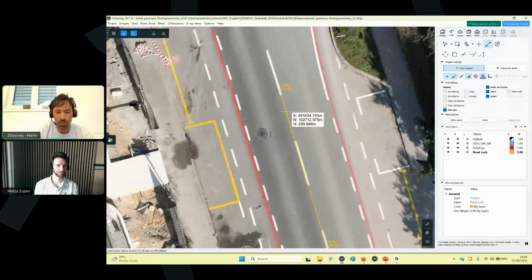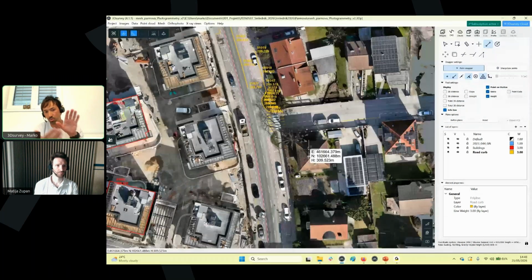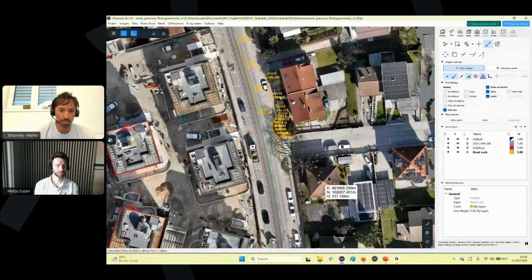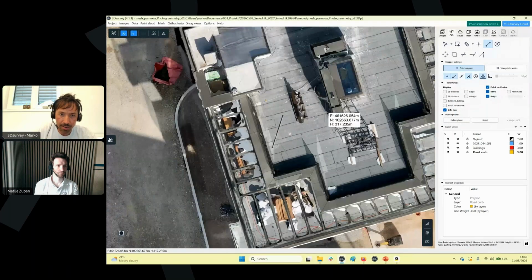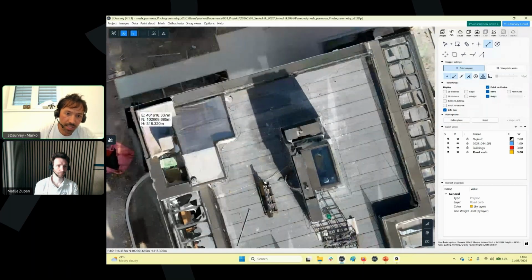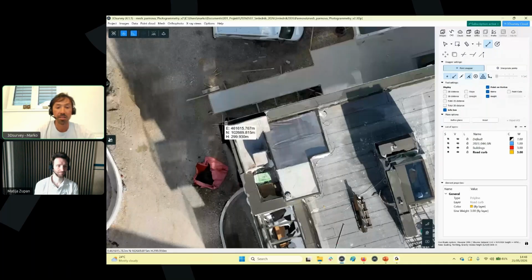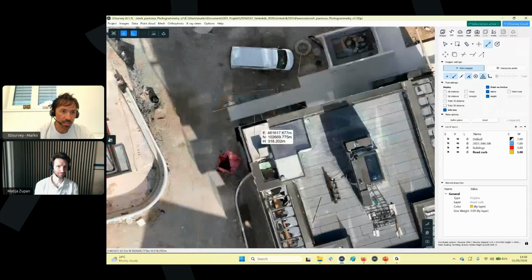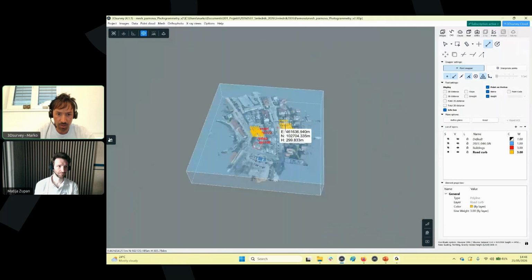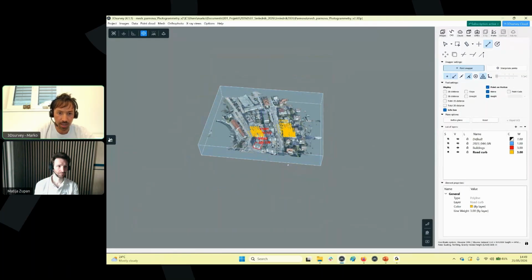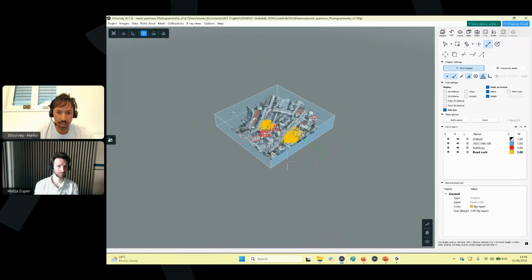This is super easy and effective if you don't care about the height. Nevertheless, if you would like to transform at the end all those CAD lines to the zero level, Mattia already showed you this part. Then with the building, if you go, for example, here and take the ortho, maybe yes, you can see the corner of the building. Maybe another option with the ground orthophoto. The third option: turn off those two settings and use the bounding box before. So like right mouse click, you see on the top plane, you can move up and down. Right mouse click on the side one, you can go smaller with this one, like that.